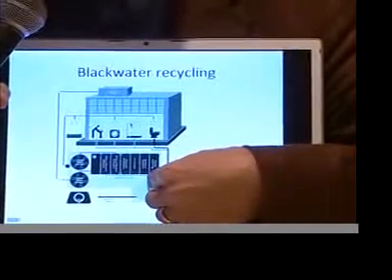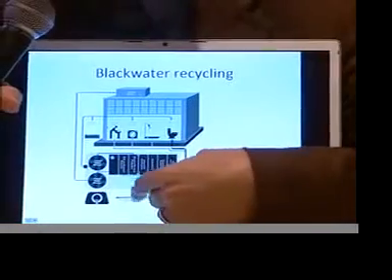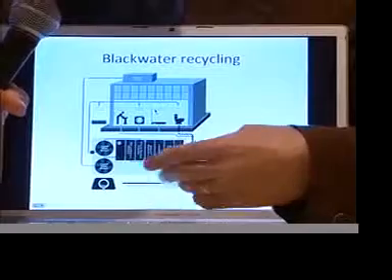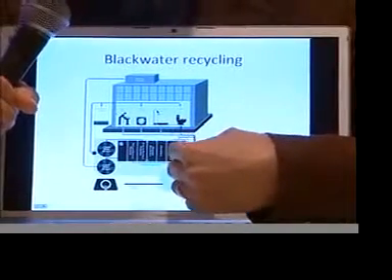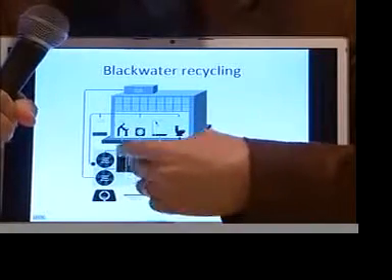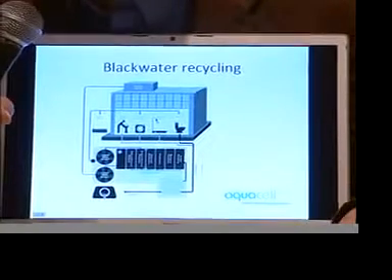And collecting it in a point. In this example, it's a sewered area. So the waste would go to the sewer if the plant wasn't operating or if it's down for maintenance. And you're picking it up and putting it through screening, biological treatment, ultrafiltration, UV disinfection, chlorine residual, and in some cases nutrient removal. There are some good examples of this that have happened in the US.